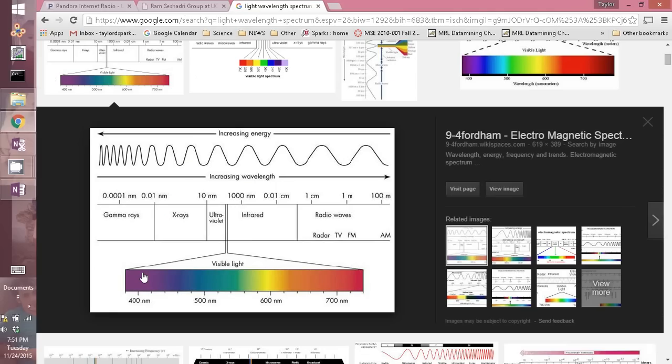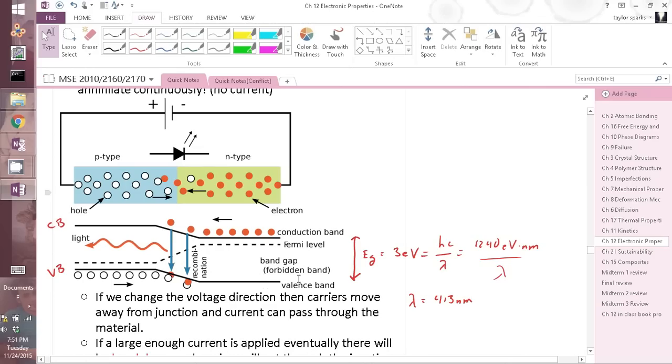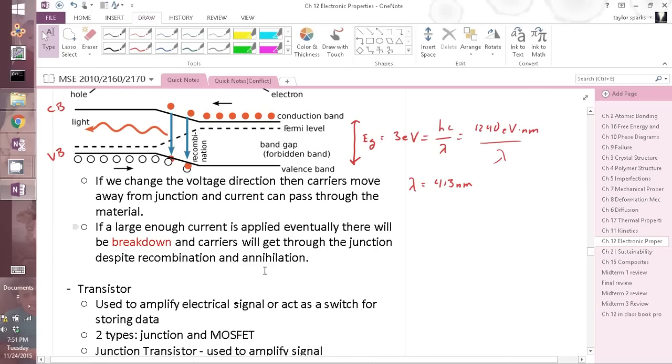If you wanted something with a different colored band gap, you'd calculate what wavelength of light you're interested in, turn that into an energy, and get a material that has a band gap near that energy. That's the basic principle behind LEDs. Now, there's a lot more to LEDs, where you have more than one species giving light off. Instead of just the band gap, you can have things that luminesce or phosphoresce, and we won't be covering that in this lecture today. Okay, but that's the basic idea.